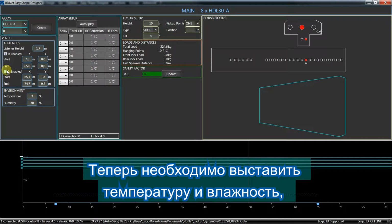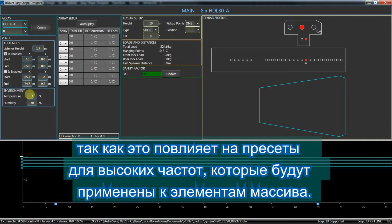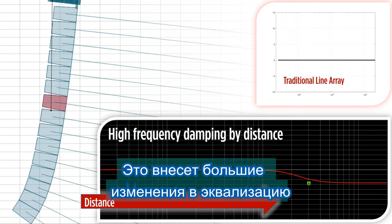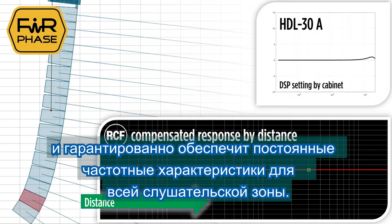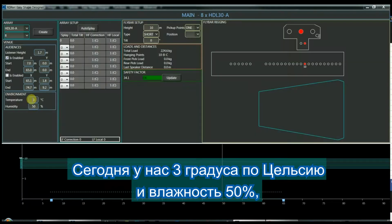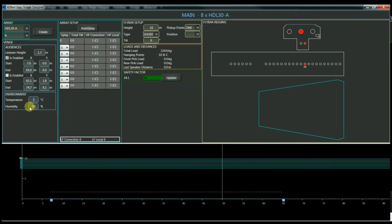Now we have to set the temperature and humidity, because this will affect the HF preset that will be applied at the modules. Very important. This will make big changes in the equalization and will ensure a really constant frequency response along the audience area. Today we have 3 degrees Celsius with 50% of humidity.